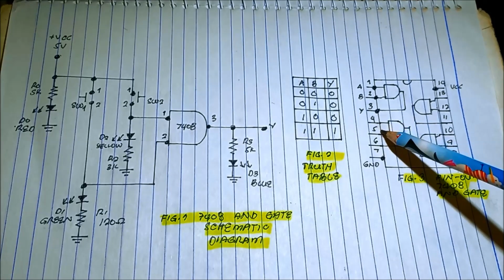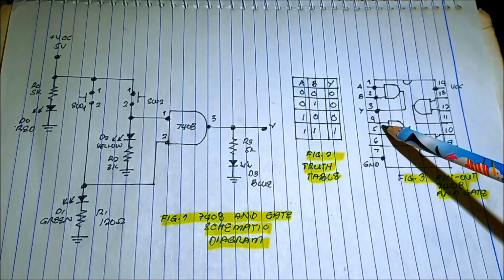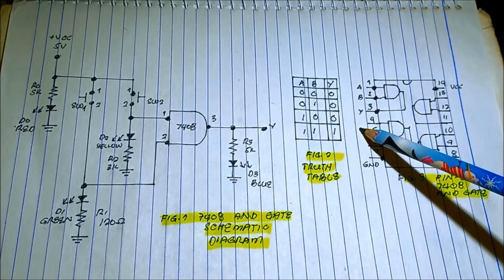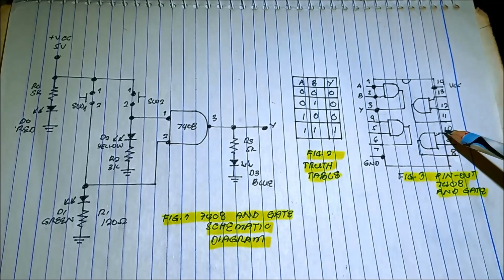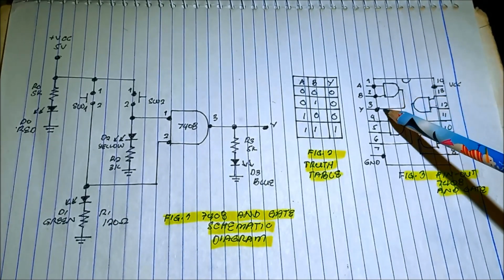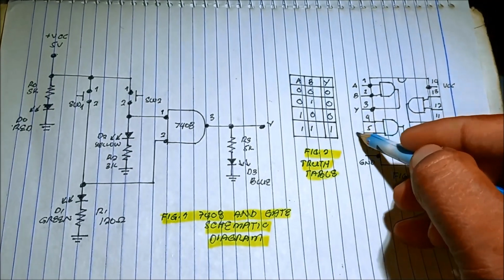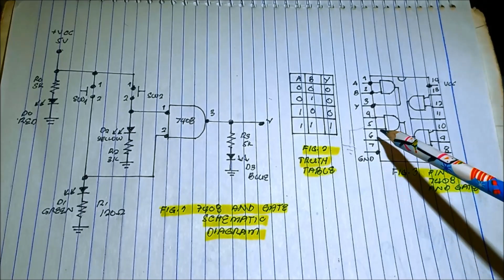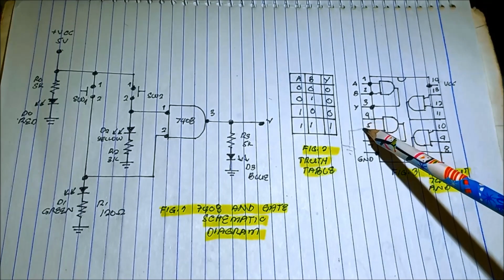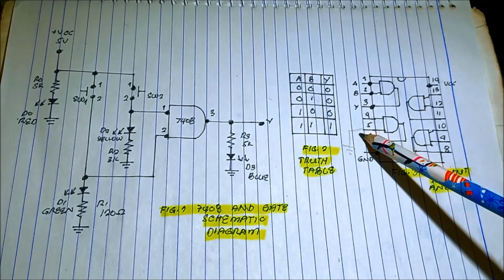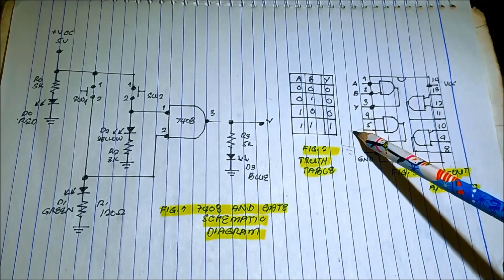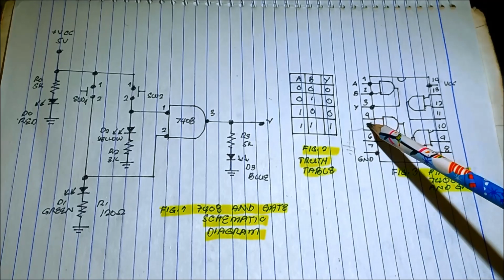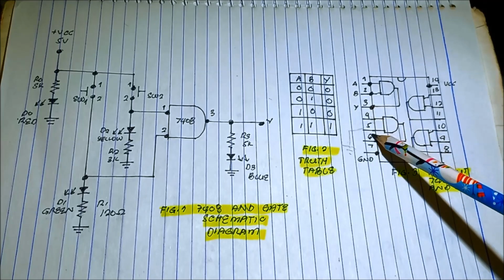The other inputs in our IC, we need to connect to the ground, just like this: pin number 4, pin number 5, pin number 9, pin number 10, 12, 13. All the inputs must be connected to the ground. Why is that? In order that the input will not float, so that we don't have a floating input. If we did not connect it to the ground, we do not know what is the condition of the input, if it is low or high level.